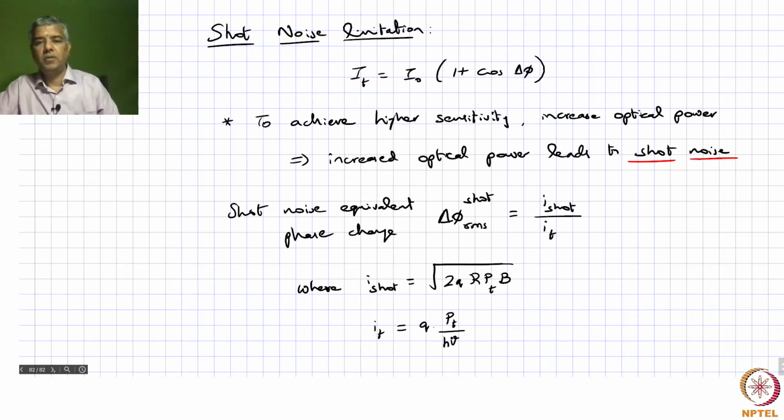So that's the rate at which light is falling on the photodiode, that's the optical flux, right. And this is multiplied by the conversion efficiency from the optical power to electron hole pairs, which is given by what is called the internal quantum efficiency. These are things that we looked at a while ago.